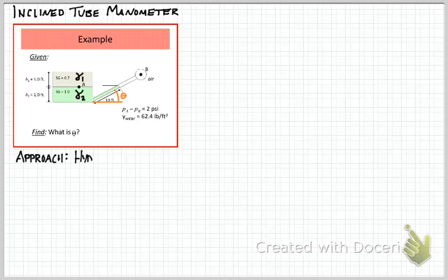So our approach to this problem is going to be to apply our hydrostatic equation to relate points A and points B. Note specifically that we don't have to start at the atmosphere, so at the surface of fluid 1. We can start working from any point that we want to, so long as we're continuous about our movements in the horizontal, which does not change fluid pressure, and in the vertical, where we do see pressures changing proportionally to the specific weight of the fluid.